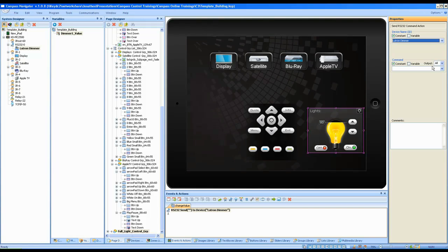And we are able to identify the command that we are sending. So we could go here, we know this was output 1, which was our ID number 8 of the system. So this correlates to the tabs that we saw in the library for the product as we're in the RS-232 manager. And we could select our command that we wish to work with, which was our level set, or volume as it's referred to here, P1.